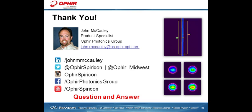And then at that point, take measurements frequently just to make sure you do not have a laser process that is changing. And then once you've established that baseline, you can kind of come off of it. Once you know that your laser system is performing like it should be, once a month, once a quarter. I've got automotive people who measure once a shift. So it really does come down to your own personal preference. But hopefully you walk away from this with some good recommendations.